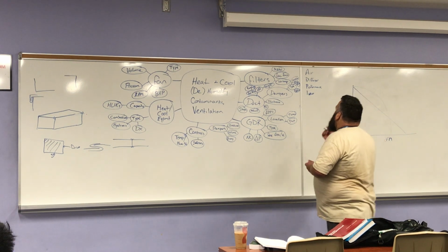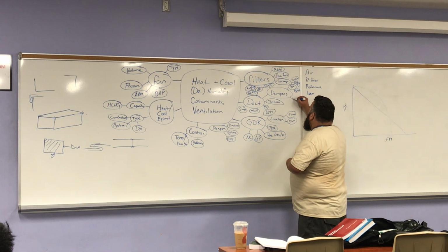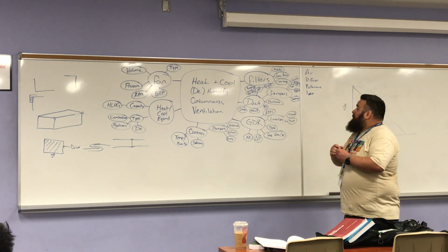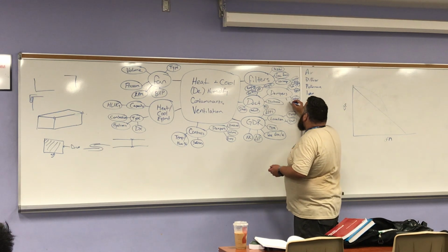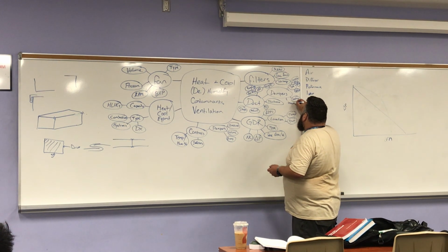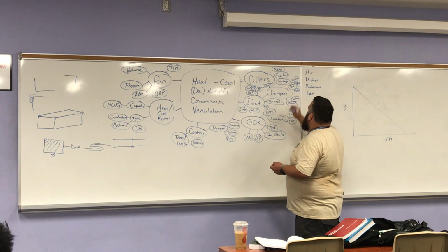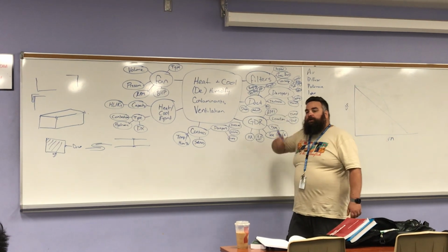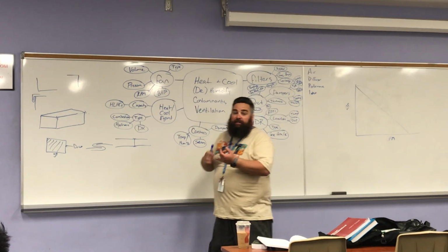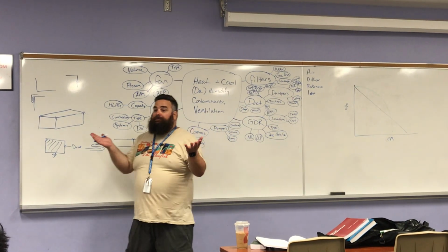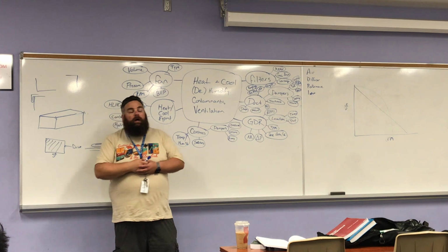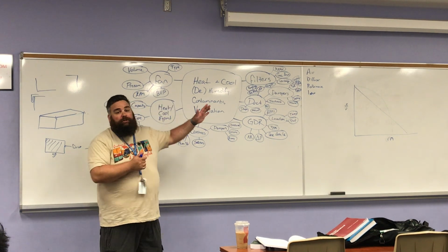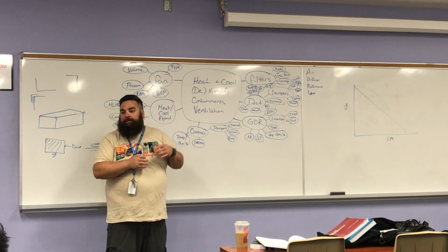Oh, leakage. We'll also put leakage. Okay. Oh, insulated. I'll put insulated with a question mark. It's something I need to consider. If I'm putting a damper in an exterior wall, I want it to be insulated because I don't want a hole of no insulation. That's not very efficient. I also want a low leakage because I don't want that air leaking into the building.